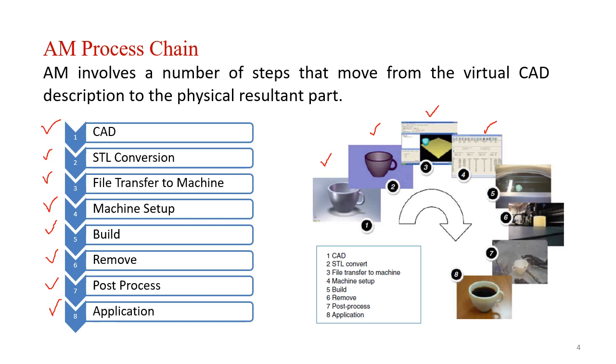Then fifth one, building process starts. So one after the another layer is getting built, and here the product gets completed after the build process is over. Then we need to remove the product from the build plate. So removal of the material or a product from the build plate happens in the sixth step. As it gets adhere or sticks to the surface, from the surface you have to remove it.